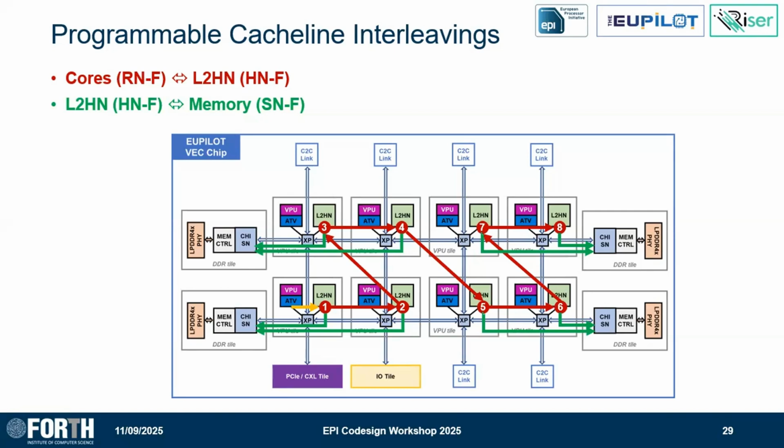Now, if it's smaller and depending on the traffic pattern, there are lots of traffic patterns and the numbers vary. So here, what we try to do is to avoid having uniform traffic scattered all around the chip all the time. By default, you will have it, but we don't want to have it. We want to have it in a form of controlled and staggered manner, predictable. If you pick your interleaving hash function with XORs, which is very common, then you don't know what will happen.